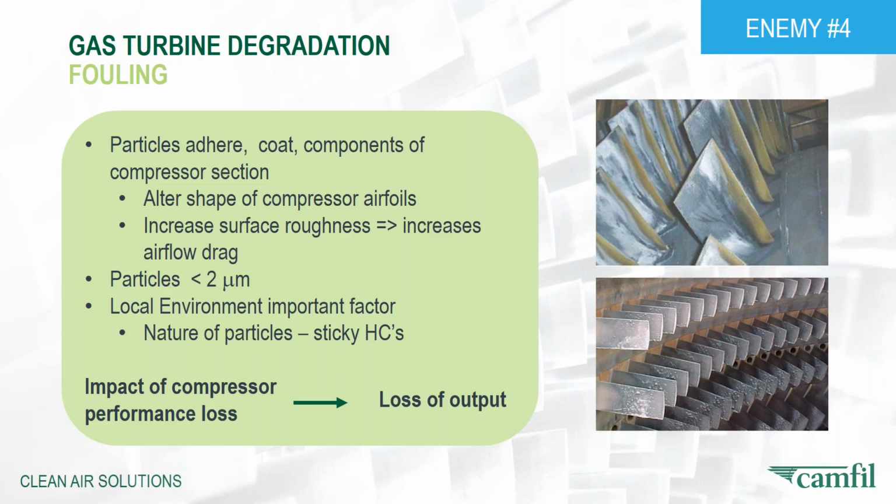In addition to the size of the particulate, the nature of the particle is also important, such as whether it's a diesel particulate or sticky hydrocarbon. The total impact is loss of compressor performance and loss of output.